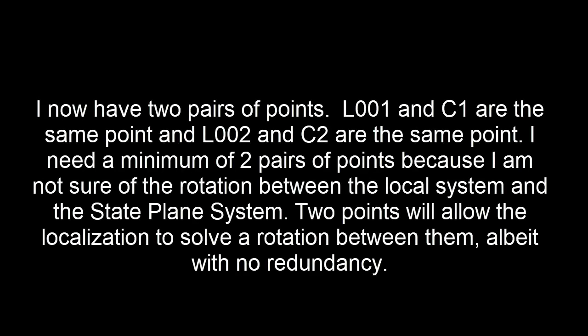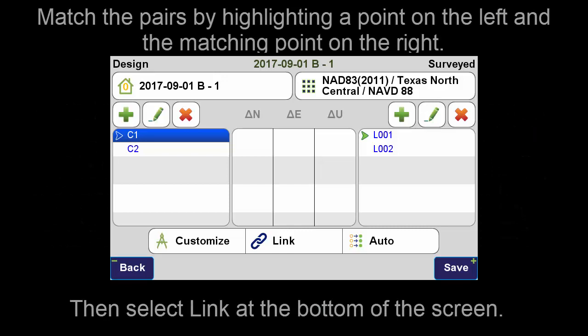I now have 2 pairs of points, L001 and C1 are the same point, and L002 and C2 are the same point. I need a minimum of 2 pairs of points because I am not sure of the rotation between the local system and the state plane system. 2 points will allow the localization to solve a rotation between them, albeit with no redundancy. Match the pairs by highlighting a point on the left and the matching point on the right.